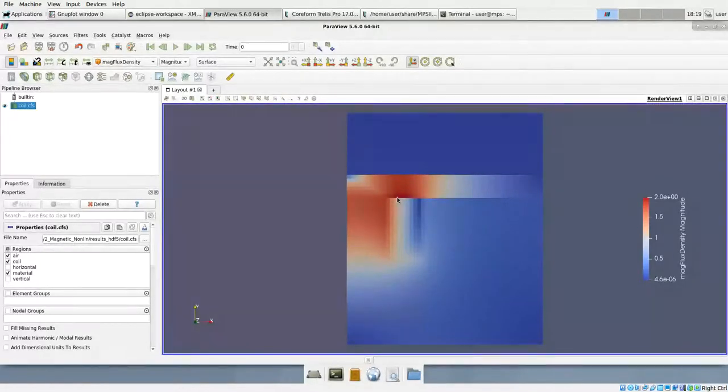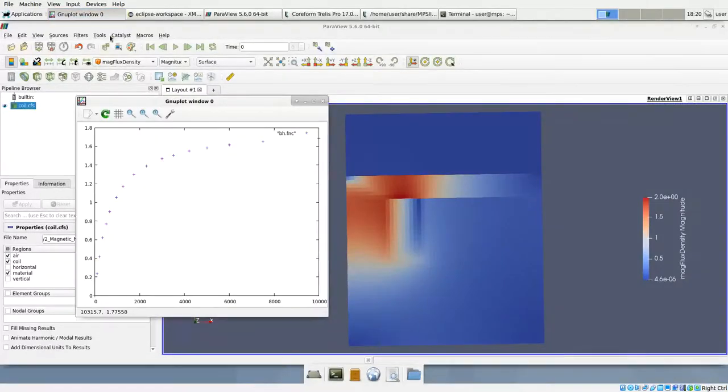So what's important to mention is that each element here has its own permeability, because this element, for example, where we're reaching the maximum saturation of 2 Tesla, has a very small permeability. The region here, for example, the blue region where we have very small values of the magnetic flux density, we're somewhere here in the linear region with a different permeability than here.